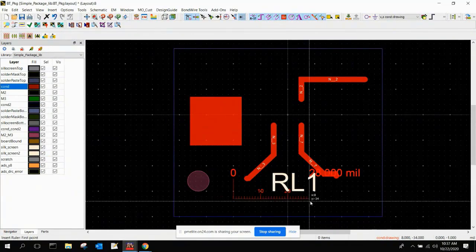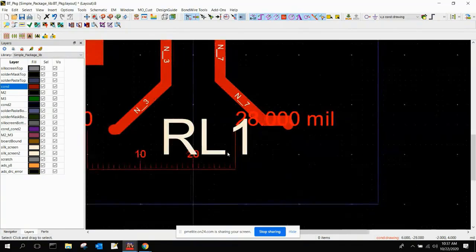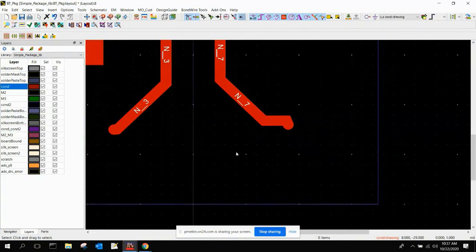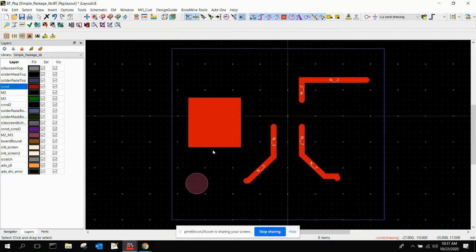I'm going to make some measurements, and the point is, this is in mils. So these databases have different units, different layers. Under normal circumstances, if I took this thing and tried to instantiate it, like I might on a chip design, maybe I have some kind of bandgap reference or something, and that's a piece of hierarchy, and I instantiate that into my larger circuit. That's not going to work here, because these things are just different technologies.